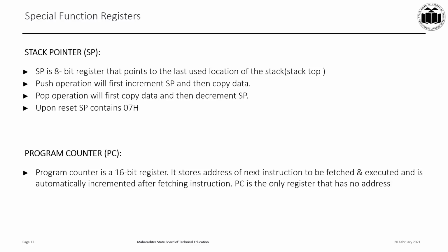Program counter. Program counter is a 16-bit register. It stores the address of the next instruction which is to be fetched and executed, and is automatically incremented after the first instruction is fetched. The program counter is the only register that has no address.